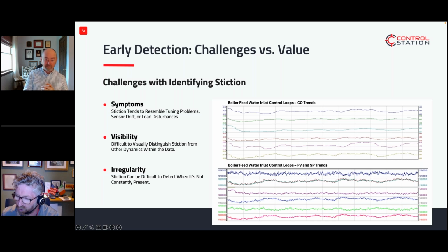I was thinking about that earlier, actually, that with batch type systems, you can get in and do a maintenance, but on those 2-year turnaround sites, you need to plan those actions in, and maybe you need to live with that degree of stiction over that time.